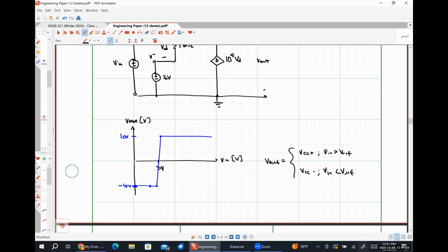Reference voltage for both. Yes, sir. So, when you just said it, but clarify, for Vin, it's so close to the reference. It has to be incredibly close. What does that make? Wouldn't it make like 0? It would make it 10^5 times whatever Vin minus 3 volts is. But I mean, it has to be within a few microvolts of the reference voltage to not saturate.